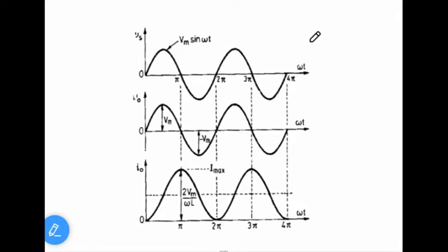Since the frequency is 50 Hz, 1 by 50 Hz is equal to 20 milliseconds. Therefore, for 20 milliseconds, you can get one positive pulse. And if it is the first question, for what duration will this diode turn on? It is for the entire cycle, meaning 360 degrees is the answer.